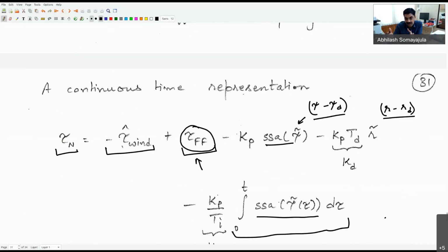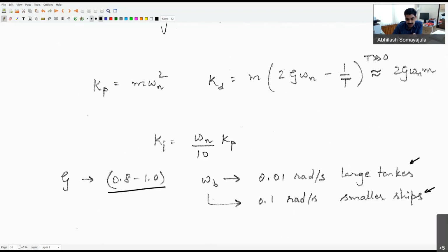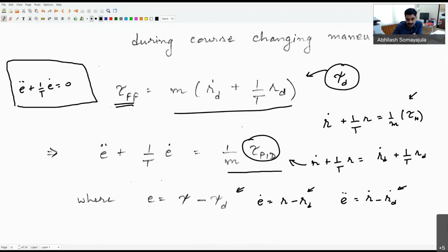Automatically the PID law will have non-zero coefficients there, which will try to push the error back to zero. My only point was that instead of trying to make sure that the system will go to a zero error using the PID control law, I'm stating that I'll provide a feed-forward term such that naturally the system dynamics will always tend to zero in the absence of any external disturbance. If there is any other external disturbance which is coming into the picture and trying to push my craft away from the heading that I desire to track, then the PID will compensate for that difference.